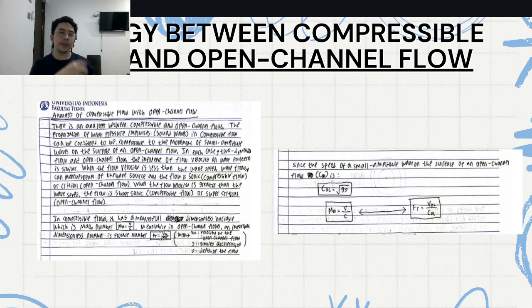Since the speed of a small wave on the surface of open channel flow is C_OC equals root of gy, we can substitute it here so that the Froude number equals V_OC divided by C_OC, which is very similar to Ma equals V per C. The dimensions are defined almost the same way, but it depends on where the application is being held.